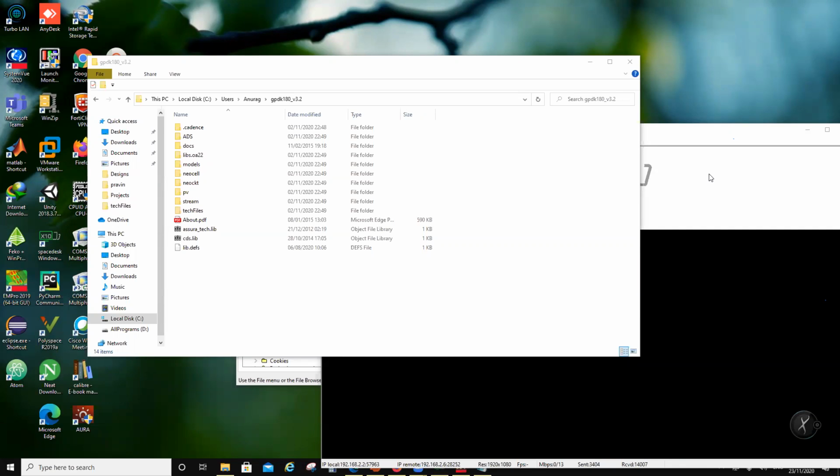If you want, you can take the touchstone file, or what you call the S2P file, from here into Cadence. For example, for an inductor, you simulate in Momentum and take its touchstone file into Cadence. You can do that. HFSS says it's a 3D simulator. It is a 3D simulator, right? It uses FEM, so that's a 3D simulation.